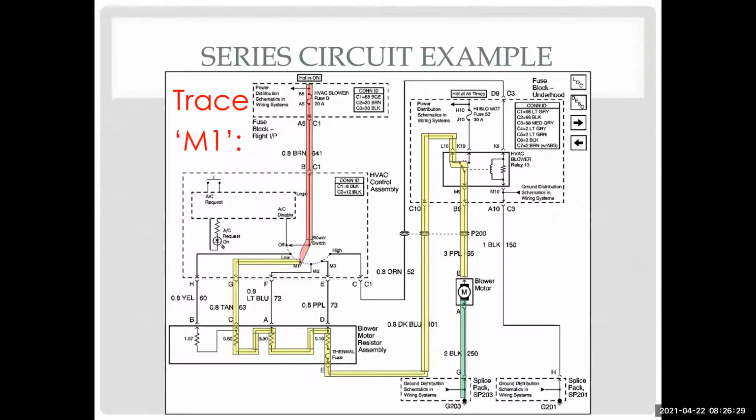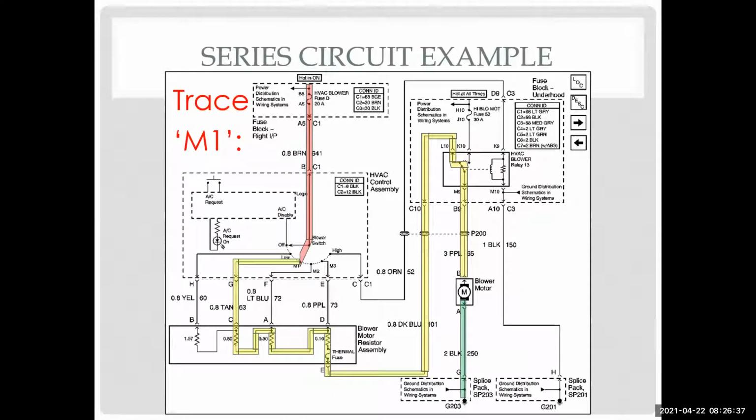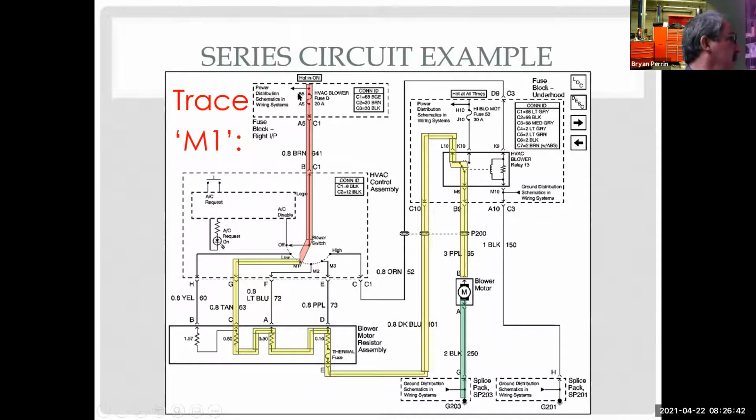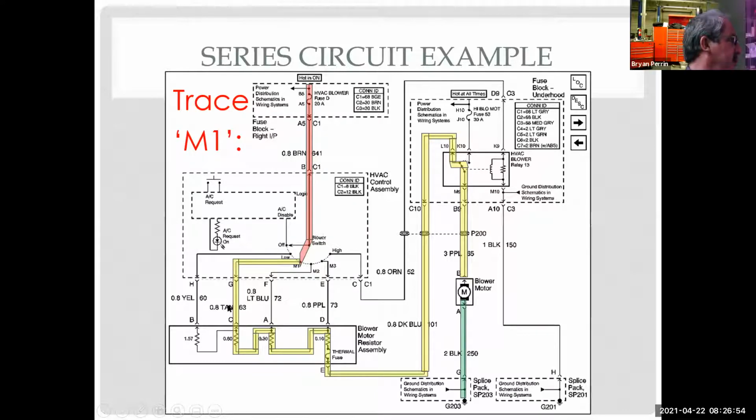Is it the red lead that's going to ground? What do you mean is the red lead going to ground? The red on the diagram, C circuit. Okay, so the red right here is just my constant power. Yeah, no, isn't it going directly to ground right after? No, no, because this is my switched power, and it goes to my load, and then it's ground after my load. So this is my ground in green.